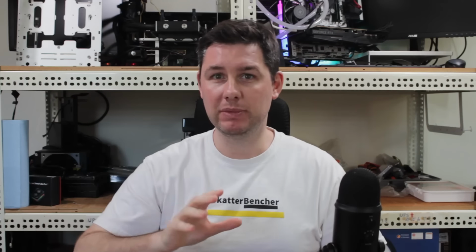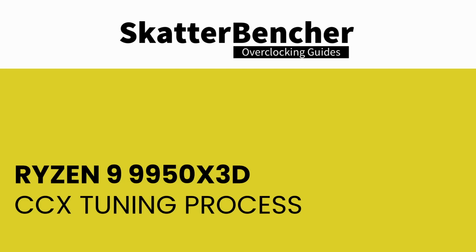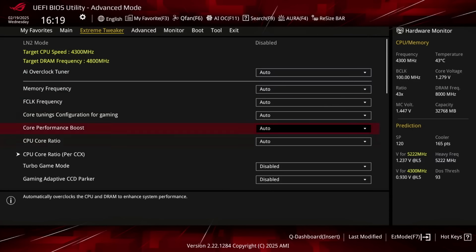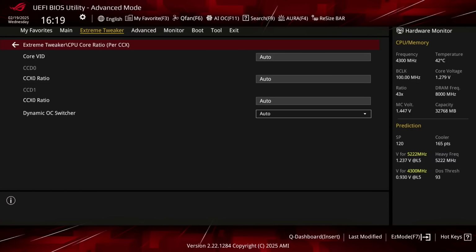The VRM load line configuration is relevant to this overclocking strategy because we're switching to OC mode and disabling Precision Boost technology. That means that the CPU is no longer regulating the load line by itself, and we have to do it manually. Choosing the right operating voltage for our manual overclock is always a trade-off between increasing the overclocking headroom, managing the new thermal challenges, and of course, considering the CPU lifespan. With that last thought, we kick off our manual overclocking process.